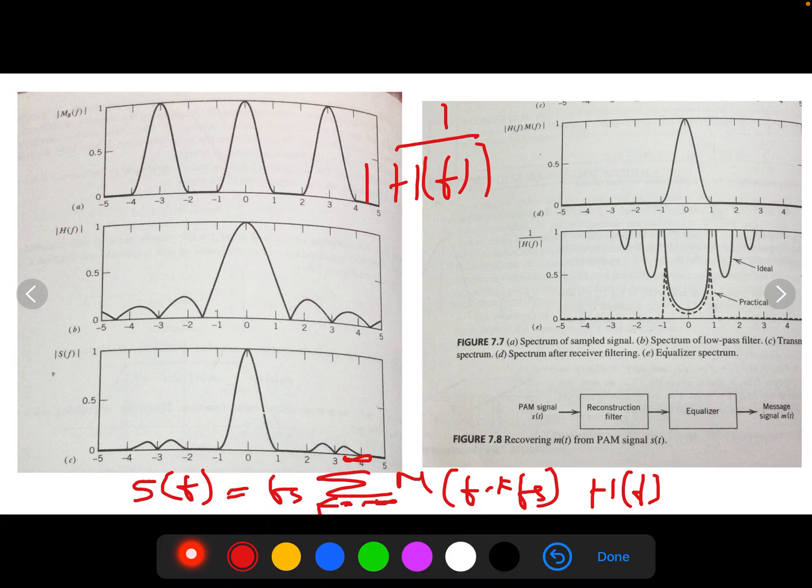Finally, we can see that the transmission of a PAM signal imposes rather stringent requirements on the amplitude and phase responses of the channel. Because of the relatively short duration of the transmitted pulses, the noise performance of a PAM system can never be better than the baseband transmission.